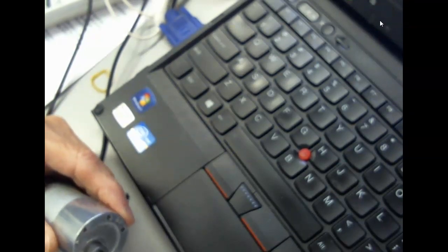Most of your PLCs have counters in them, and they have quadrature encoder counters. So we just bring the two inputs on this thing into the PLC, and it would count up and count down. We could also count over a certain time and use that to calculate speed.